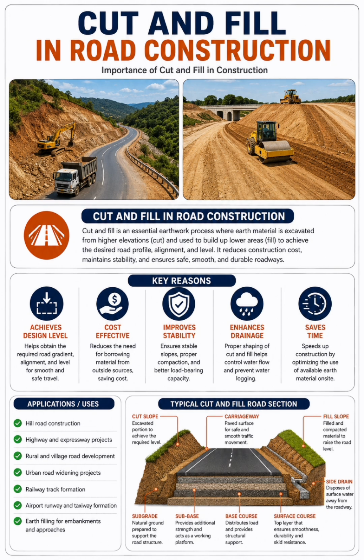So here we'll be taking a look at the cut to fill in construction, and the importance of cut and fill in construction. Cut and fill in road construction is an essential earthwork process where earth material is excavated from higher elevation. So when you're considering your cut, that means your elevation at that particular area is high. So maybe what you require is just 3 meters, and you're having about 8 meters. So you are going to do a whole lot of cutting, which is about 5 meters depth of cutting, and the material is used to build up lower areas.